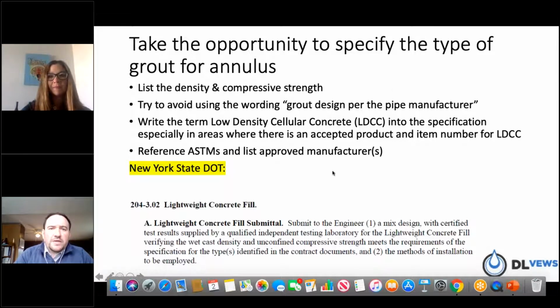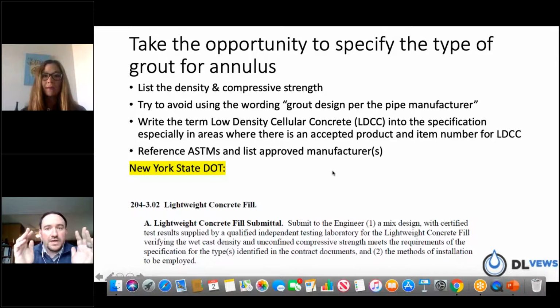Not specific to Reline, but as a really good correlation for the folks on the call, I have some municipalities here in the Northeast that are switching their pipe abandonments, that's gas, water, sewer, all their abandonments, to cellular grout because they know they can pump it hundreds of feet successfully. So instead of 10 holes for that 1 mile stretch, they might only have to open up 2 or 3 to do the same thing.